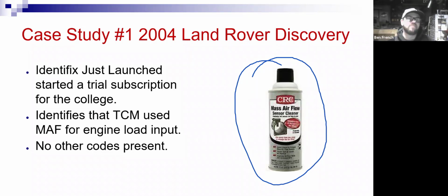So I felt pretty good with that, okay, really it was the mass airflow sensor. And we put a $300 or so mass airflow sensor on the car, fixed the problem. So the transmission slippage code wasn't related to the transmission at all. It was the mass airflow sensor. And I couldn't have done that without service information and my scanner and really thinking about it.